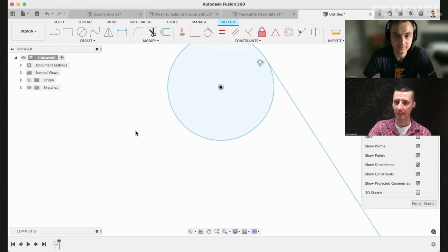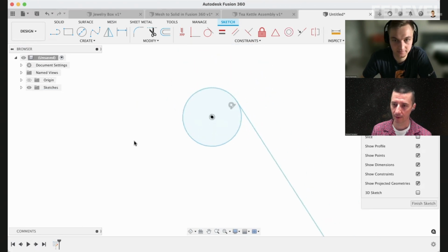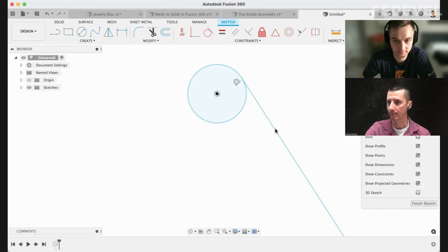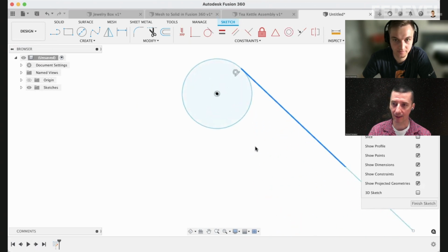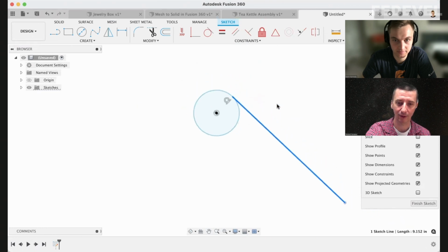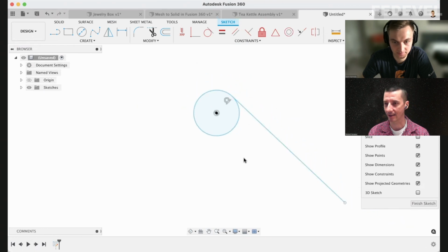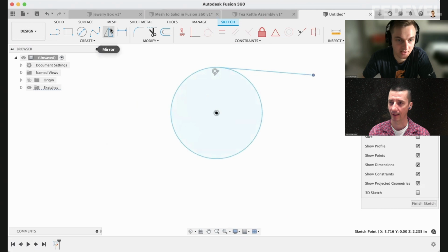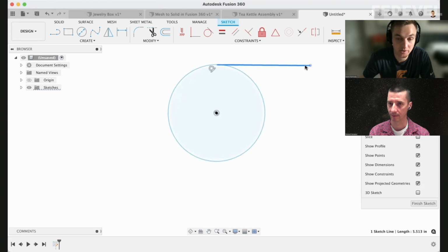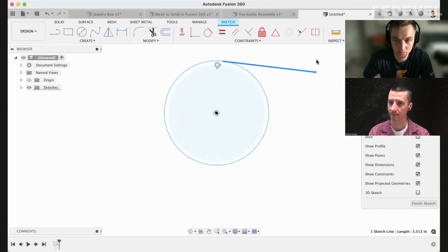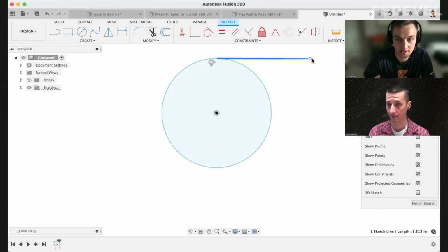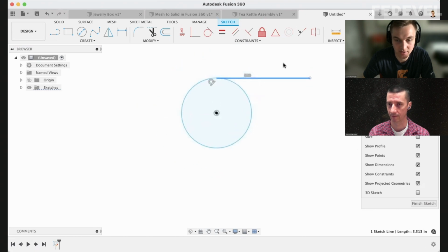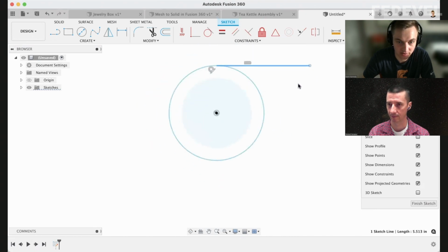Okay. So for example, in this case, we could, I don't know, specify the distance between the middle and the end of the line, and we could specify the diameter of the circle. Yep. So we could add, yeah, or here, let's say we want this line to be horizontal. Okay. Because for whatever reason, maybe we're connecting it to something else. So we can add a horizontal constraint there. So you'll see now I can no longer move that any other way, but our circle's still moving.